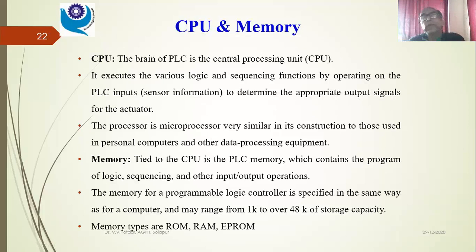It executes various logical and sequencing functions by operating on the PLC inputs, mainly the sensor information, to determine the appropriate output signals for the actuator. The processor is a microprocessor, very similar in its construction to those used in personal computers and other data processing equipment. Memory is tied to the CPU, and it is the PLC memory,